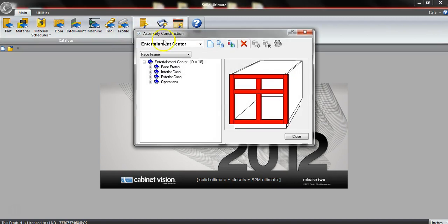Assembly. This is really important. So as you'll see here, I have entertainment center, kitchen overlay, kitchen inset, one I did for my buddy. These all came with a program already, and this is just every different way that we build a cabinet. So entertainment center, toe kick, the face frame goes to the floor. It is the toe kick. Inset, there's a toe kick, sits back, so it's 4 inches off the floor, but the mid rails here are 1.5 inches instead of 1 5/8.